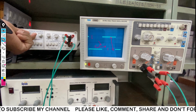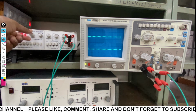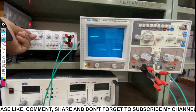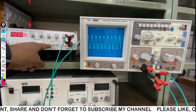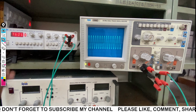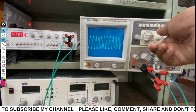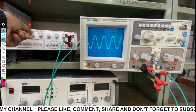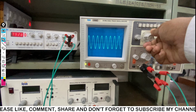You can see here, if I change the frequency, the time base knob has to be adjusted according to the frequency on the signal generator. So I am making the frequency very small. You can see the effect on the CRO. It is the same for the sine as well, as the square was showing. This is actually for the sine. If I minimize the waveform and if I maximize the waveform, we have to adjust the time per division knob so that we have at least two crests or two troughs.